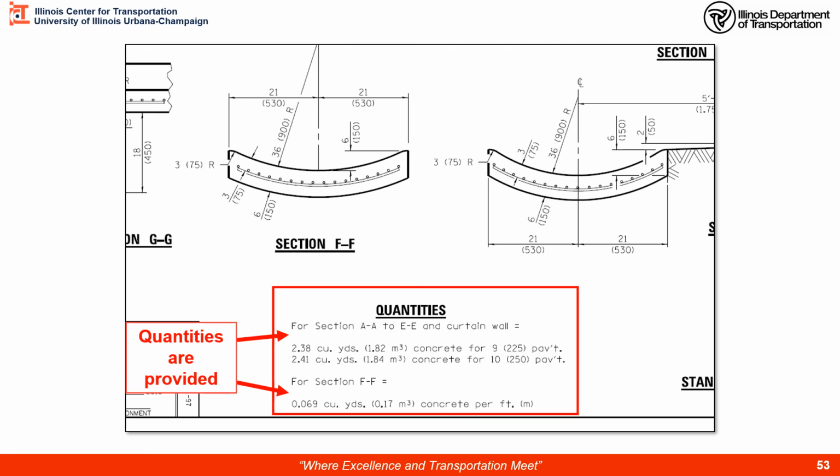So make sure you correctly have the right thickness that you're using. And then for a length of FF, you need to measure that in the field and calculate the cubic yards accordingly. In the case here, you have thicknesses, so you'll have to also do a depth check to ensure that you are getting those thicknesses.